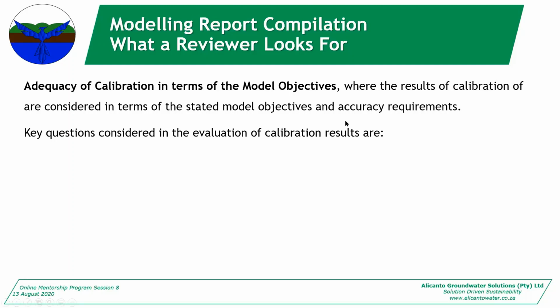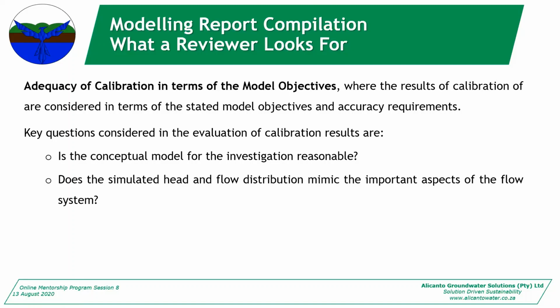The key questions when we look at our models or calibration: is the conceptual model reasonable? If you've simplified a multi-layer system into a two-layer system, that's not reasonable. Does your simulated head and flow distribution mimic the important aspects of the flow system?